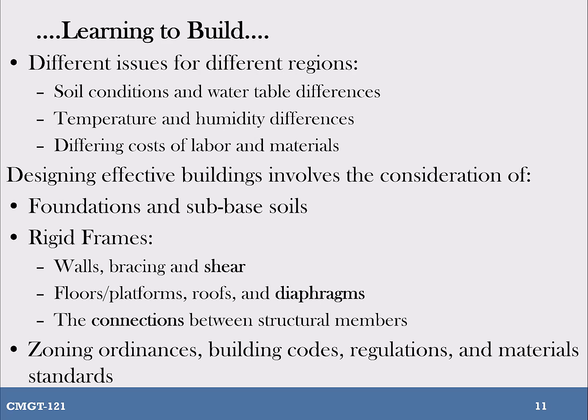There's different costs of labor and materials at different parts of the country. For instance, up where I lived in Western Canada, cedar was cheap and everywhere, and so it was a very, very common building material. Here in Louisiana, it's relatively expensive. Meanwhile, brick is very expensive where I lived, whereas here in Louisiana, brick is relatively inexpensive. And the thing is that brick is a really good durable surface on the outside of a house or other buildings in this environment, because of the bugs, because of the mold, because of the moisture.